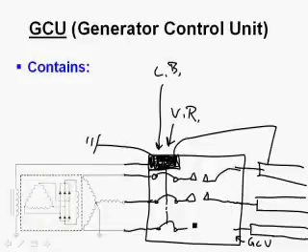We're going to have a relay. You're going, Mr. Johnson, that looks like 3 relays. Well, you're absolutely correct. So I'm putting these dotted lines together. This relay is going to be connected so that when you energize one coil, all 3 of these close. This dotted line means they're physically connected but not electrically connected. So it's going to close all of these at the same time to connect the generator to the bus bar.